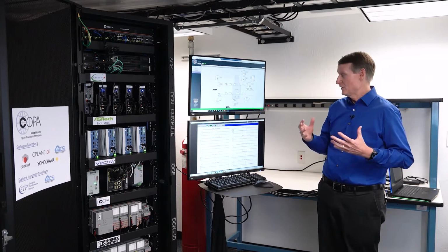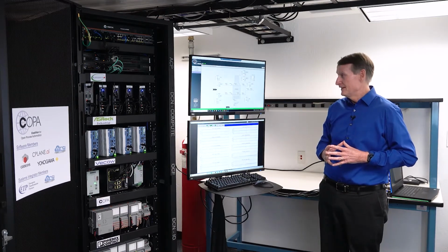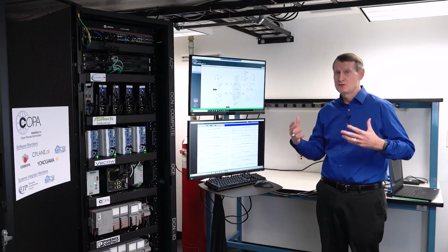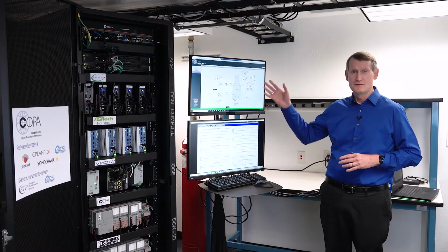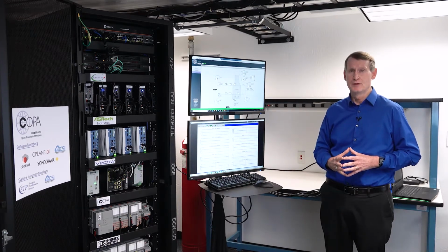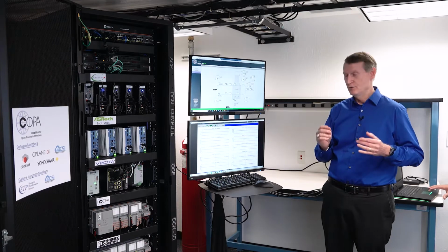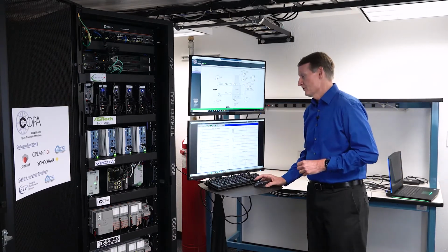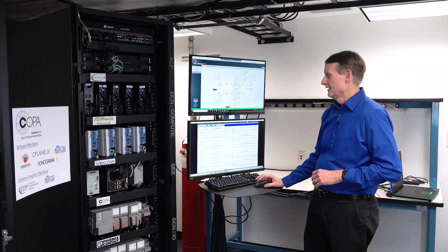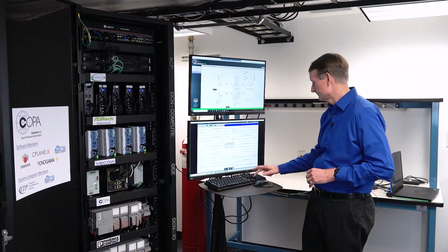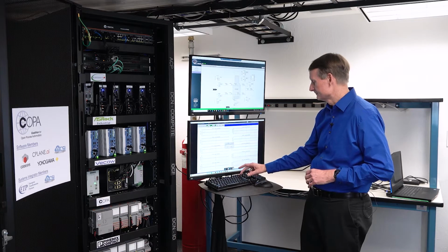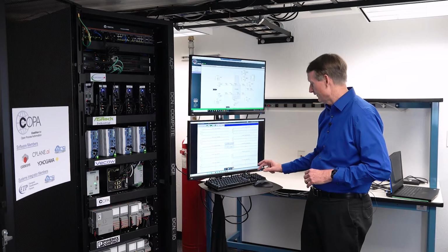And that's a little unsatisfying because, you know what an operator would do to get around that situation. And what we're going to show you is that model predictive control can resolve that in a much more effective way. And that's what we're going to do right now. We'll do the same experiment. So the model predictive control is running, and I'm going to change the outlet temperature set point up to 790. Very carefully.